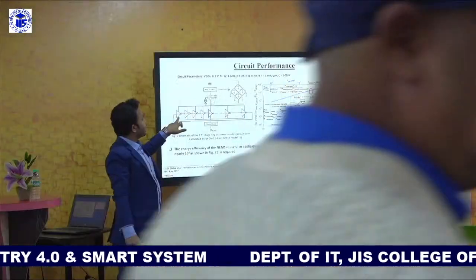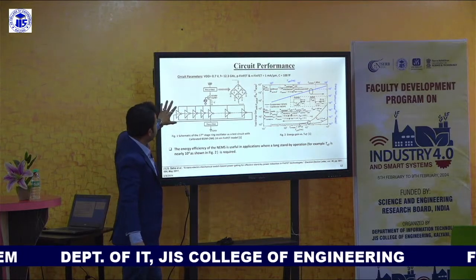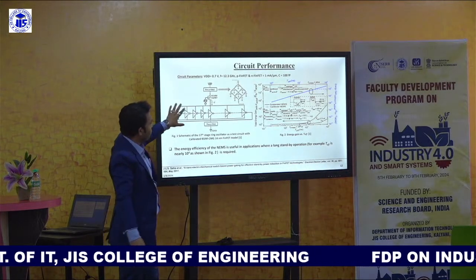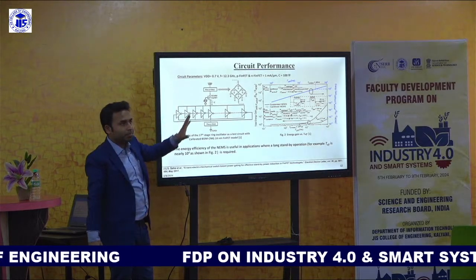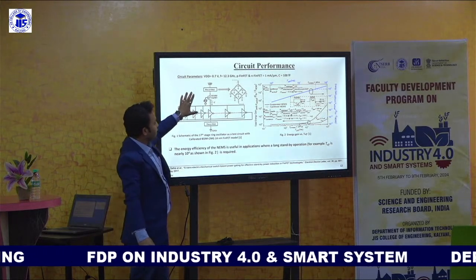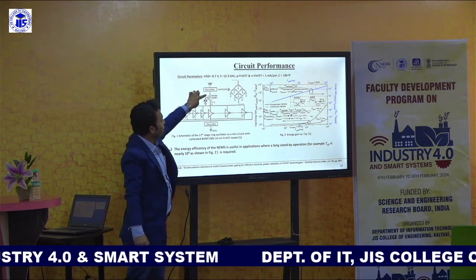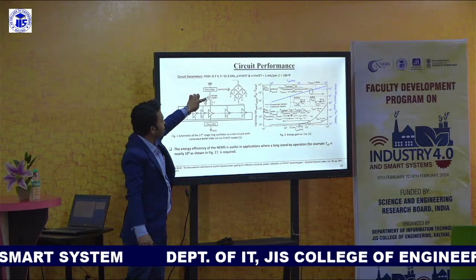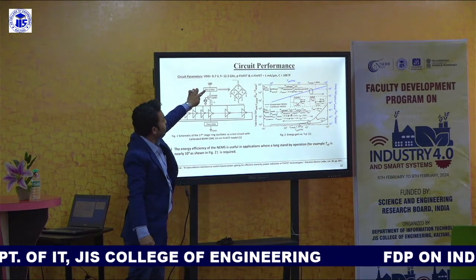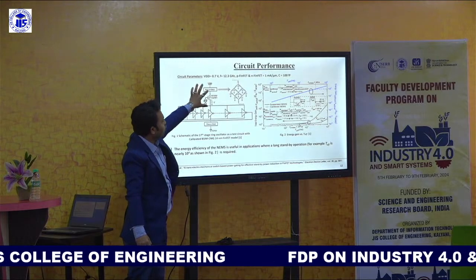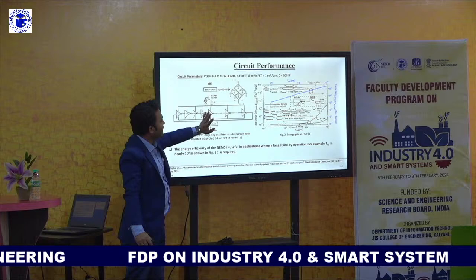In the case of this 17-stage inverter chain, if you design it in any circuit software, there are some mechanisms to reduce the leakage. The common technique is power gating. If this power gating switch is off, then the path from VCC to your circuit is off, so there is no leakage current.